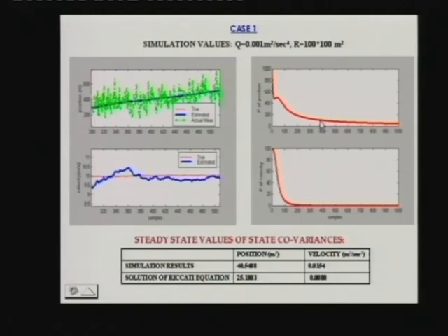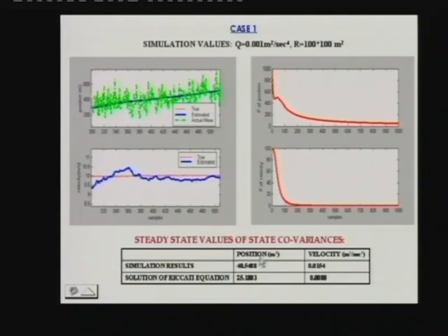So this is important, because in some other cases, as you shall see, the convergence will become significantly slower, and for good reason. The convergence means how sure the filter is becoming about the signal properties. When the filter converges, whatever doubt it had, it has also learned. So at some point of time, it has learned whatever was there to learn in the data. It cannot reduce uncertainty beyond that. So the faster the convergence, the faster the filter learns. Okay.